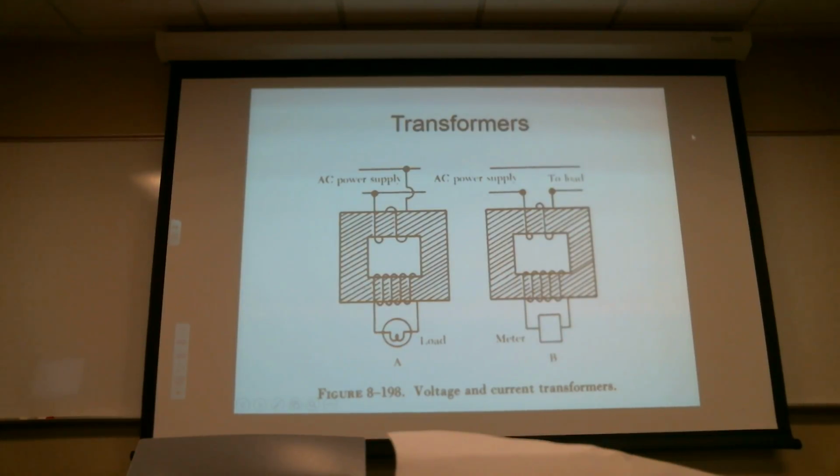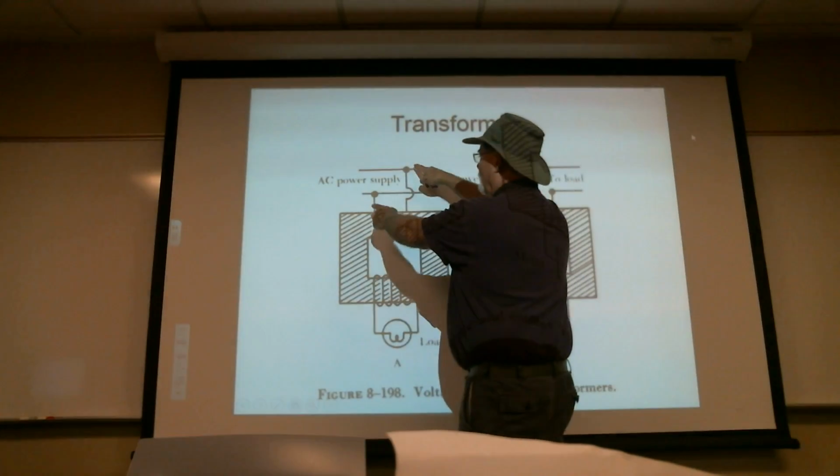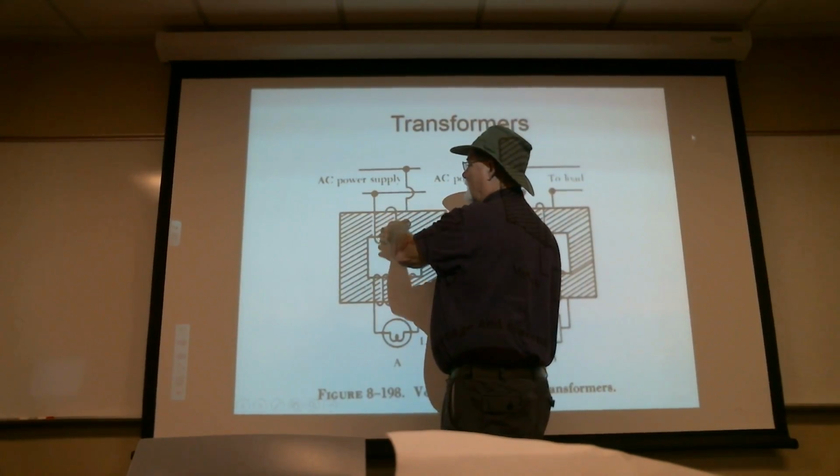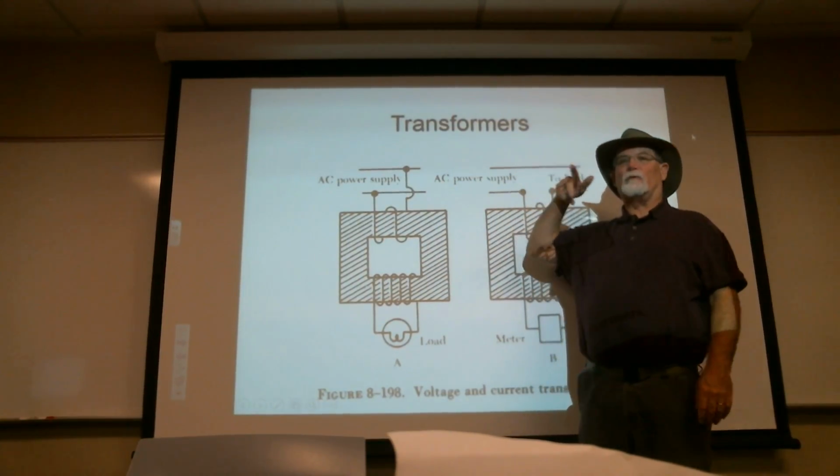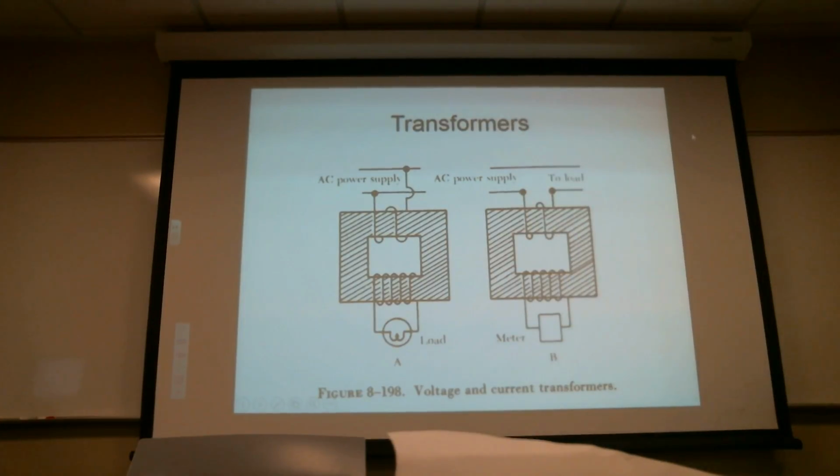Now, most often we do what's on the left side. So what will come to the plug socket will be, these two wires will come out and your plug socket's right there, and you're plugging into that. And somewhere these two lines run into the main bus in here, and they run into it in that parallel manner. But if you look off of there, each one of those are paralleling off of the two lines. It's very rare that we do the Christmas light thing there.